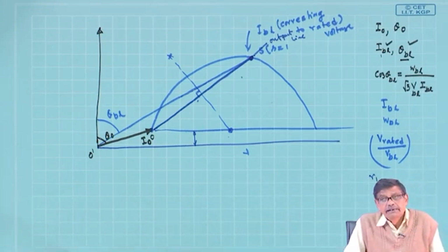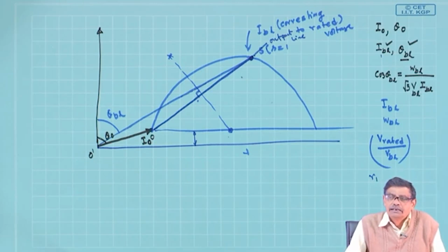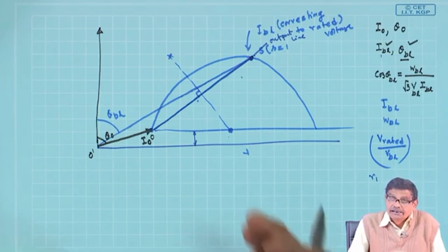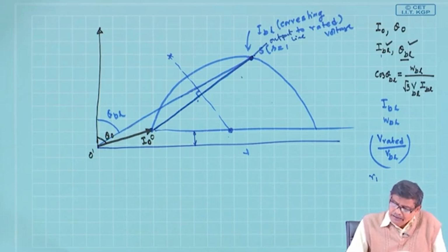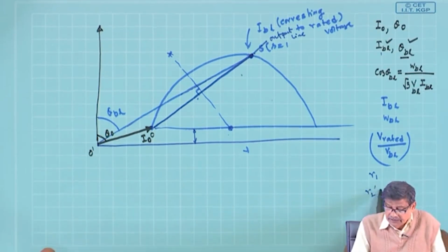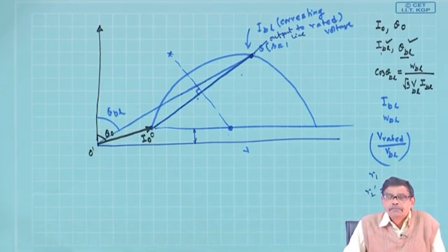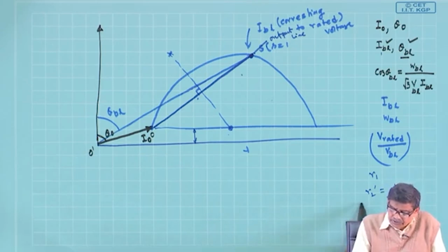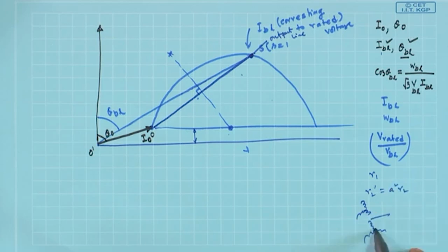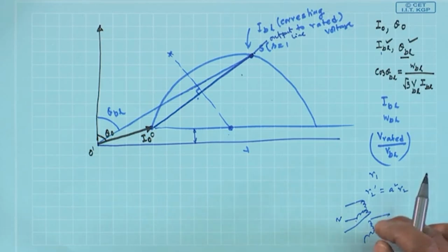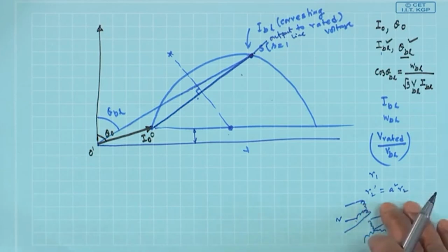Now, R2 dashed, if it is a wound rotor induction motor, similarly I can excite the rotor winding from a DC supply, get the value of R2, but I need R2 dashed. What to do? R2 dashed is equal to a square into R2. What is a? a is the turns ratio. So, for that what you do, if it is a slip ring machine, you can do it very simply. You apply AC voltage here, rotor open circuit, and measure this voltage. Are you getting? The ratio of these two voltages is N1 by N2. I am not going there. So, it can be estimated.